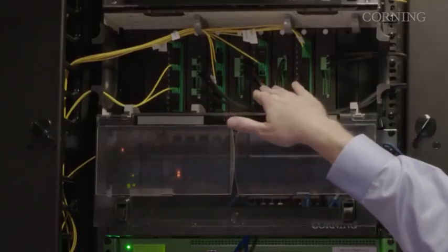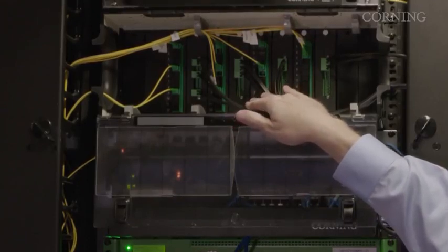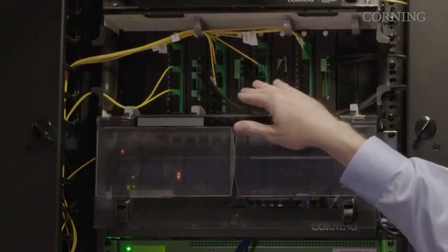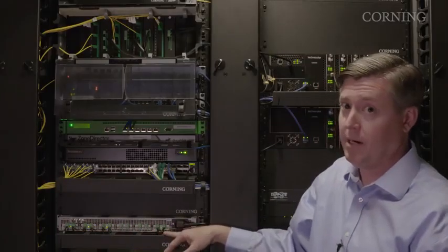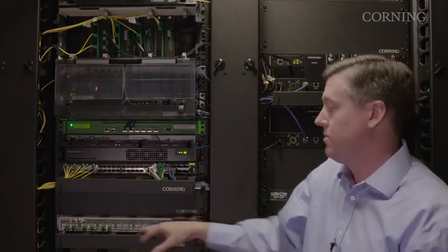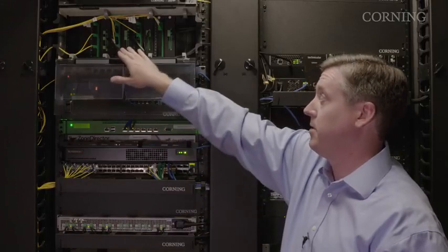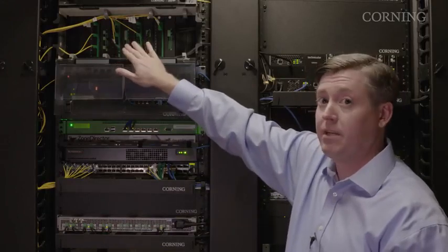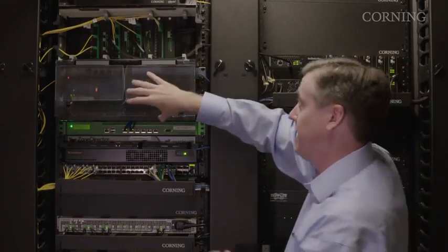This is where I'm injecting power, because on all of these locations I'm injecting both fiber as well as power to power those end devices. That power is coming from the power supply unit, Corning's power supply unit, or the PSU. So these are 100-watt circuits which are patching from the PSU up to the patch panel, leaving out the back via composite cable.